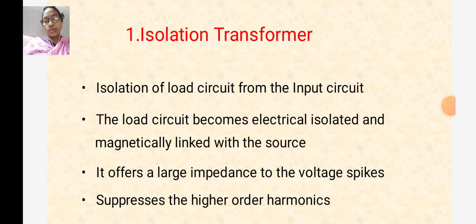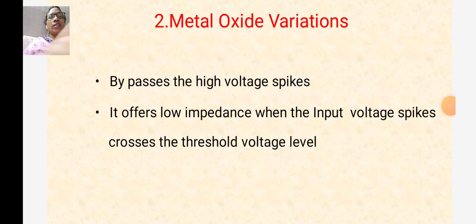In this, it is used to isolate the load circuit from the input circuit. The load circuit becomes electrically isolated and magnetically linked with the source. It offers a large impedance to the voltage spikes, hence it suppresses the spikes and the higher order harmonics.